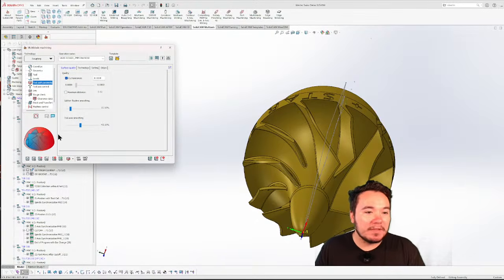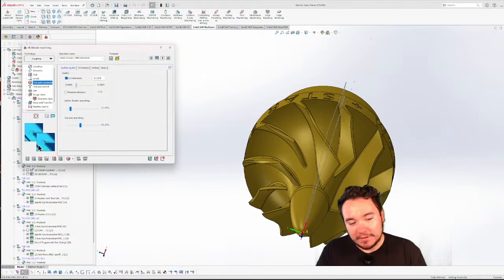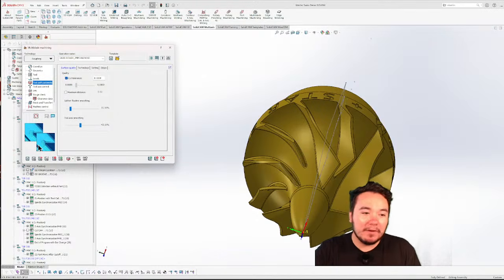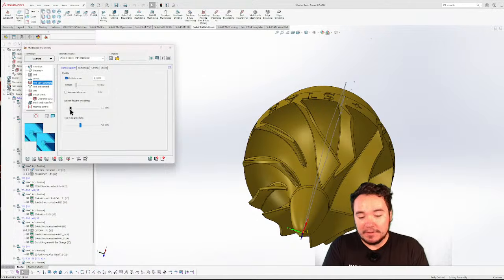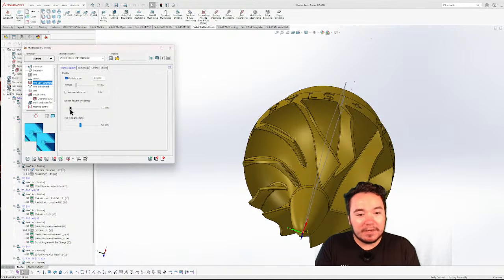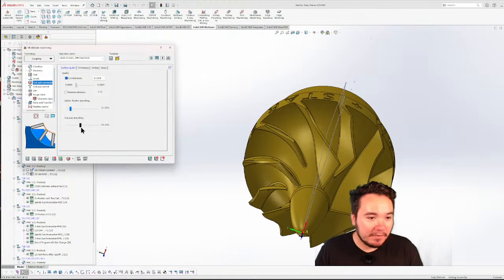Toolpath parameters, I messed with the splitter flow line a little bit, and what that is, is whether it's going to be nice and smooth, or if it's going to stop and go around it, which is what I wanted to do. If you do more splitter flow line, I saw that it would split the tool path, so it didn't come as close to the tip of the blade there. So just playing around with it to see exactly where it would go and what I would get with different choices is what I would do.